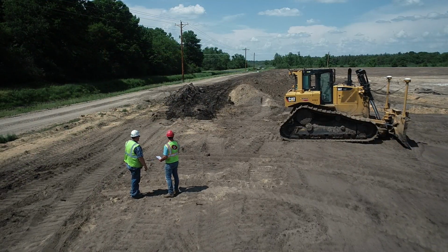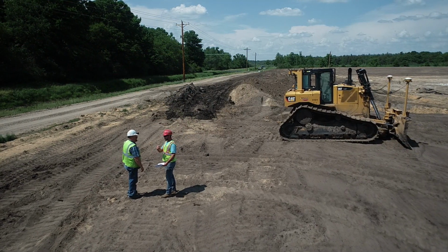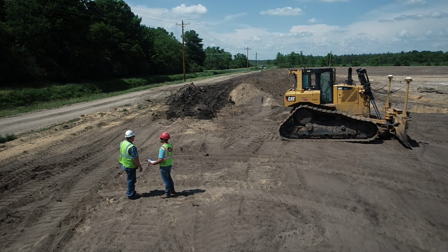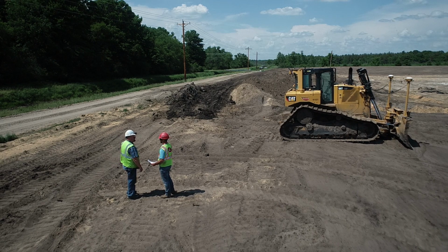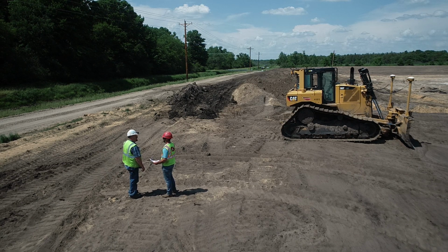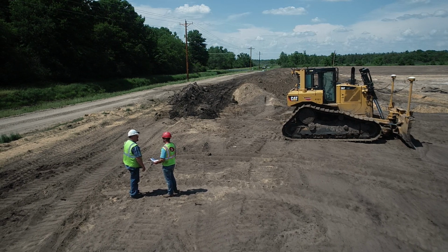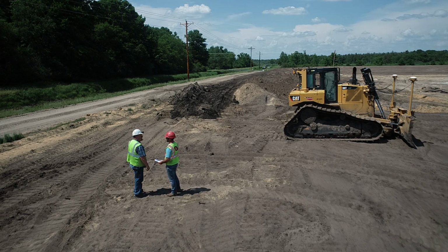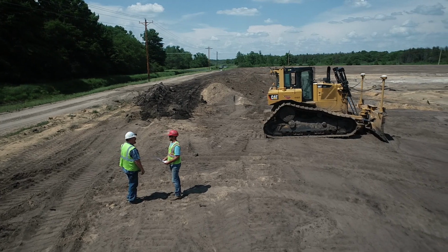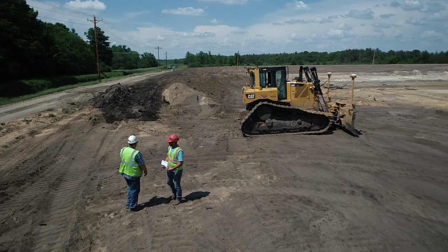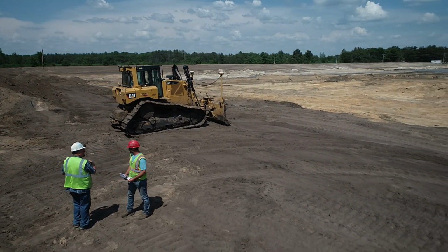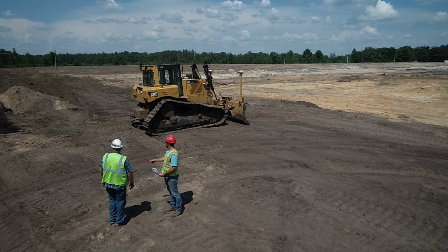Daily operational planning. Attend the pre-shift meeting to find out relevant operational information along with any known hazards or situations relating to the task for your shift. Dozer operators must receive direction from the supervisor and plan their work before commencing the needed tasks. Plan your travel route identifying traffic patterns, be aware of personnel working in the vicinity, and other equipment in the work area, conveyors, skid steers, loaders, haul trucks, or excavators.